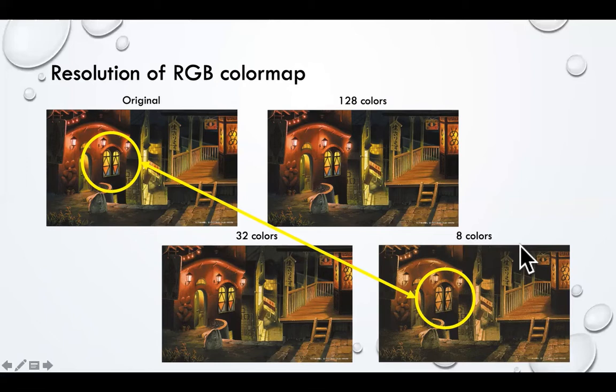So I would suggest that when you download the color map, you get as many colors as possible. In the previous NCL color maps, there are some that only have 100 colors. If you have 256, I would suggest you use 256. Otherwise, after you download it, you have to interpolate.